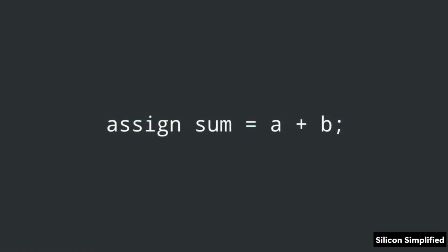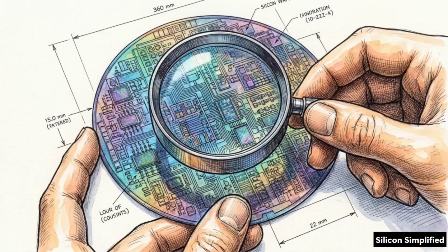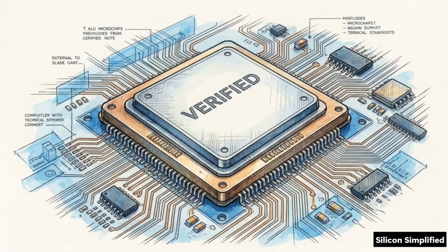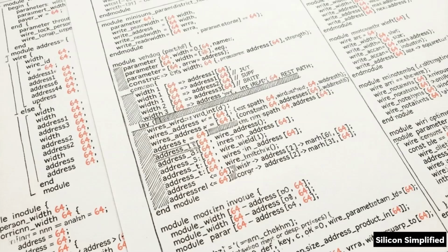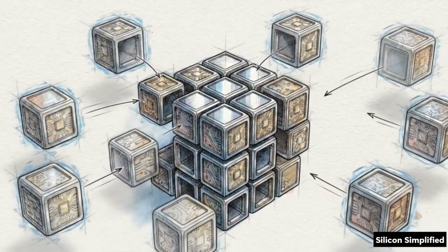Relying on manual instantiation forces a trade-off between structural control and design agility. Hard-coding every connection creates a brittle codebase that cannot easily adapt to changing specifications. Instead of placing each component by hand, the hardware can assemble itself algorithmically based on a set of logical rules. To achieve this, the IEEE 1364-2001 standard introduced a dedicated structural tool, the Verilog Generate block.